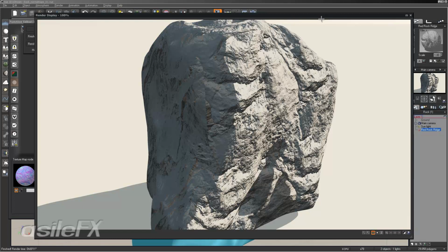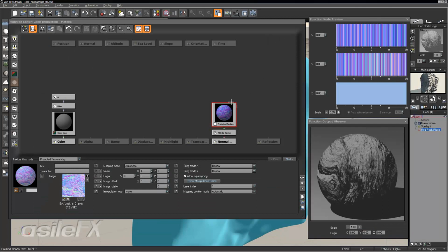And our mode is set to the automatic and modes for the different mapping types. And this is going to cause seams to show up in certain areas of the rock. Even though we do have, in this case, a seamless texture, it will still generate certain seams unless we use a spherical map in a spherical mapping mode for this texture. In most cases, it's really not going to be something you're going to see, especially if you have smaller rocks throughout the scene.